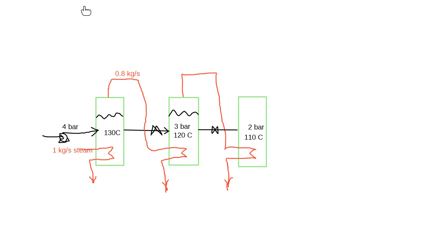As we go on, we have these different effects. Just going back to finish off this one. And of course, here we might have several effects after that, and we're going to talk about that in the heuristic now. All right, so that's how we're using 1 kilogram of steam, and here we are evaporating 3 kilograms of water out of this stream.